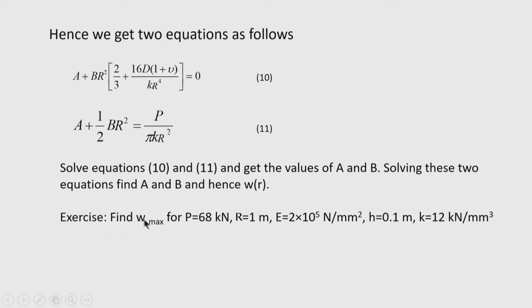The maximum deflection will be at the center, because it is symmetrically loaded and resting on the elastic subgrade, supported by the subgrade, but at the edge there is no support.